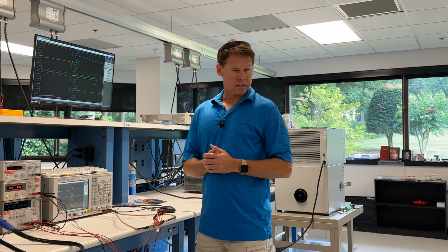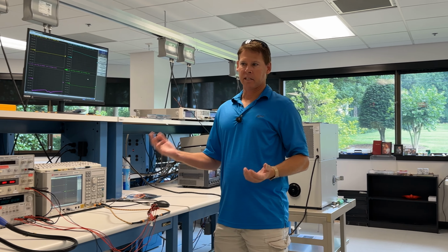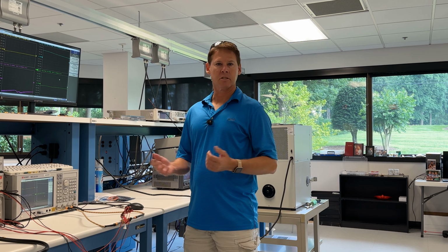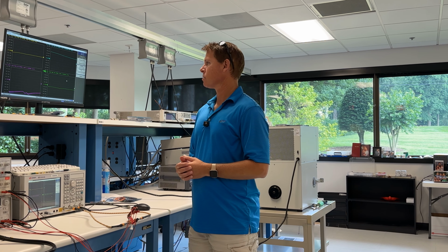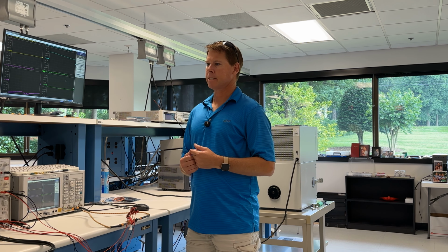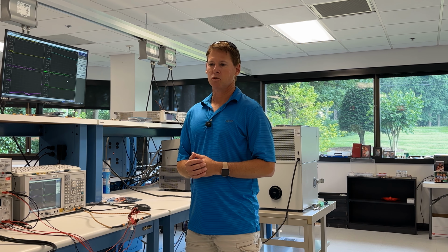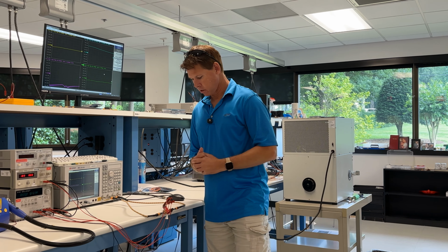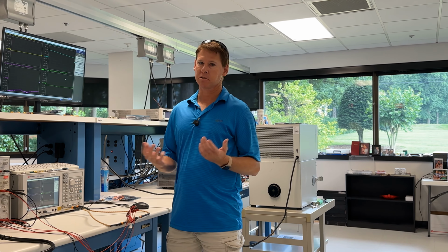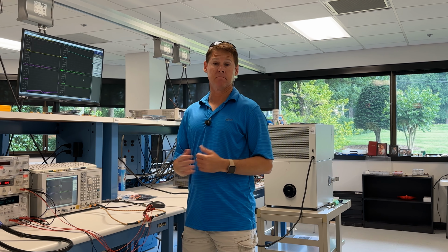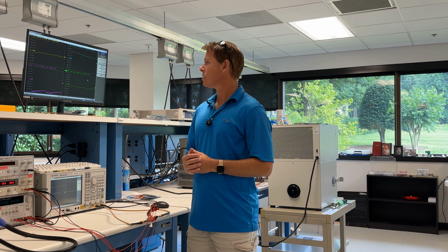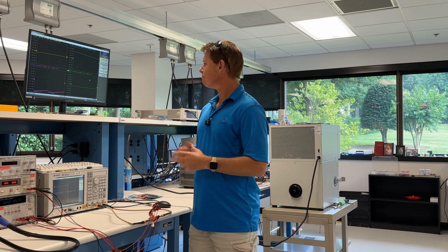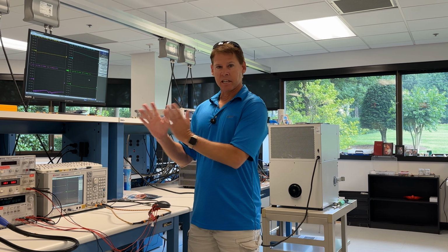The idea is to take those S parameters and I can pull them into simulation software. We use ADS and use matching elements in coordination with these S parameters to try to get as good of a match as we can across any section of this bandwidth.